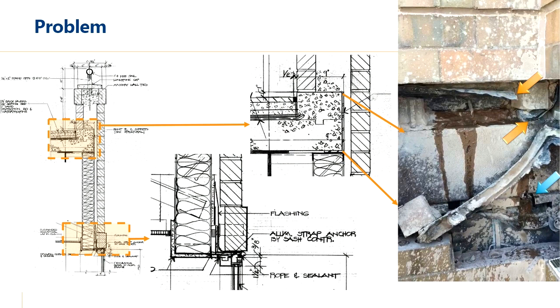At the image on the right, we are looking through the wall at the floor level of the balcony. The middle piece of that is a bent plate. That's the floor. Above the orange arrows, we're looking at a PVC flashing, which was typical for that time period but is generally not used anymore. You can see that's not continuous where those orange arrows are.